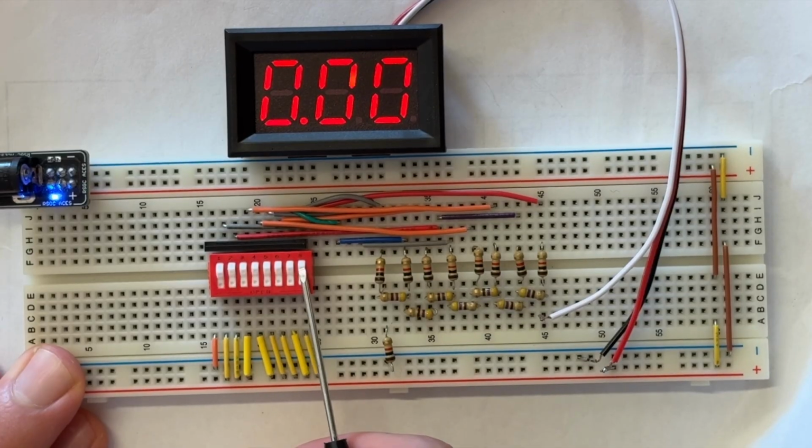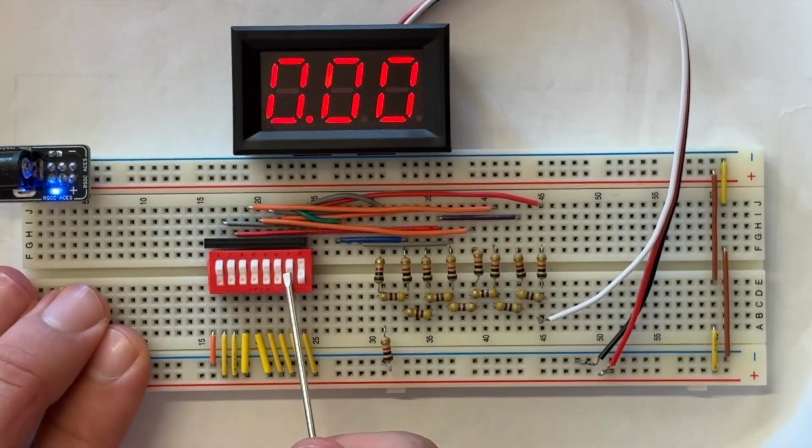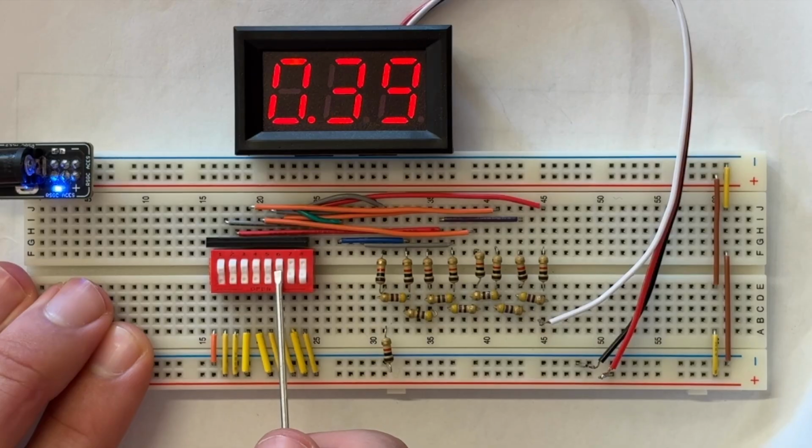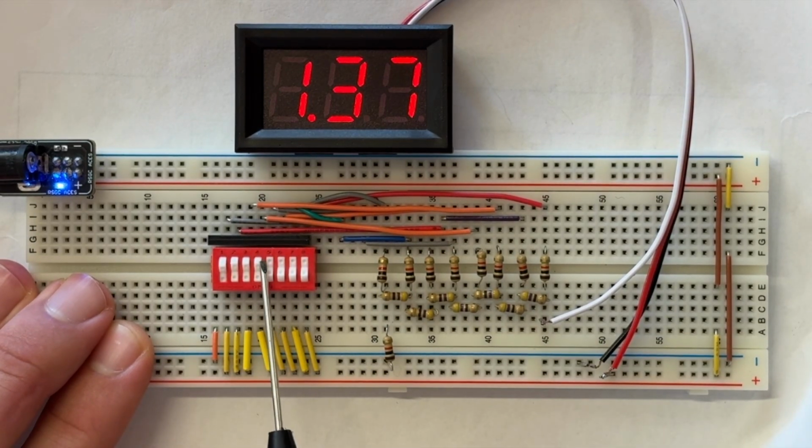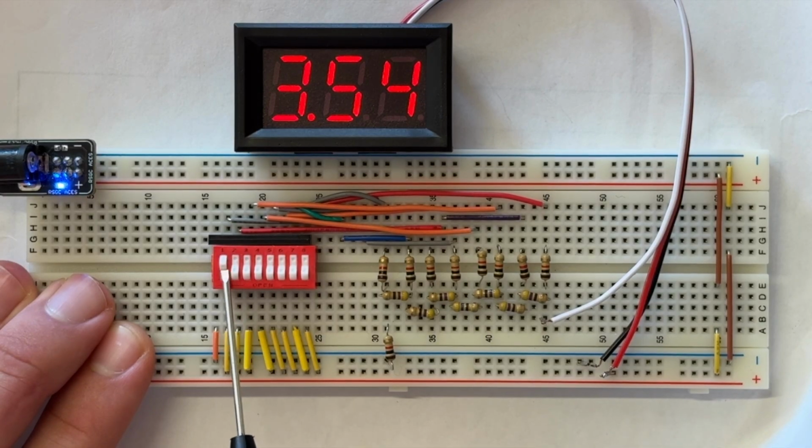This is the breadboard prototype for the digital to analog converter. Each switch represents a single bit from the most significant on the left to the least significant on the right. When a switch is flipped on, it sends power through a specific branch of the resistor ladder network. The combinations of these on and off signals creates a binary number.